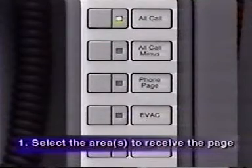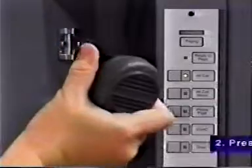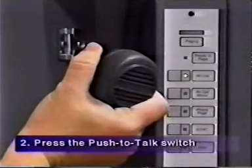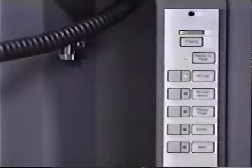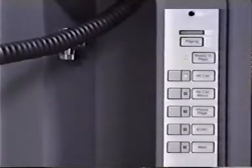The switch's LED will light steady when the system is ready to receive the page. Press the push-to-talk switch on the microphone. The ready-to-page LED will flash while the pre-announcement tone is sounding. Begin the announcement once the ready-to-page LED is on steady.